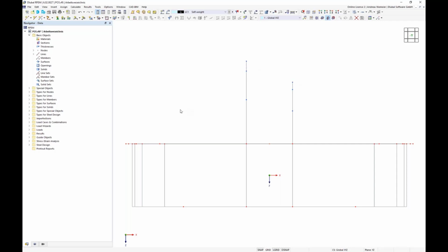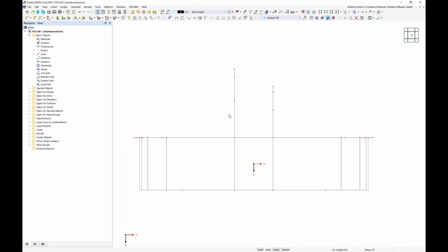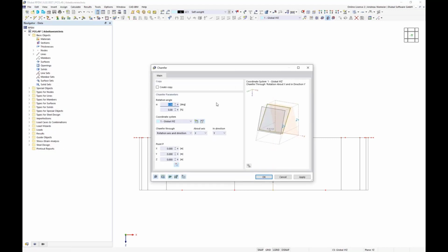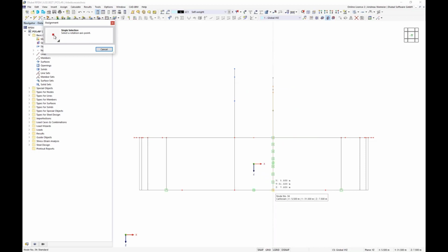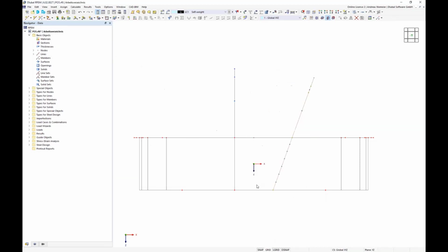And for this option, our program offers a camber function, and here we select the full arc, go to Edit, use camber, and say here, for example, -20 for the right one, and rotate around the y-axis, and move the nodes only in x direction around this foundation node. And with confirmation, the arc will be moved, but all these nodes remain on their level. So, and the same we can do for the other side.